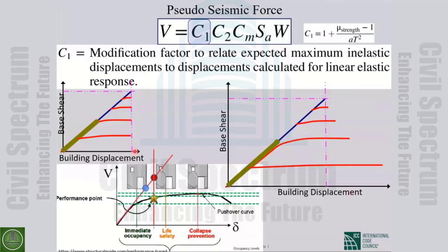That threshold is, as a general view, the period of the soil. A building is on a soil. We estimate the period of the soil, and if the period of the building is more than the period of the soil it is resting on, then the equal displacement approach governs.